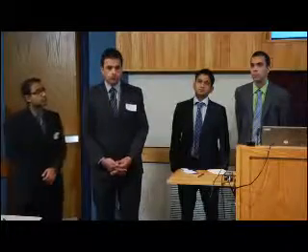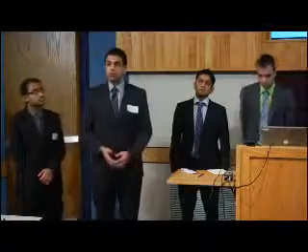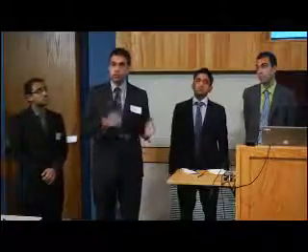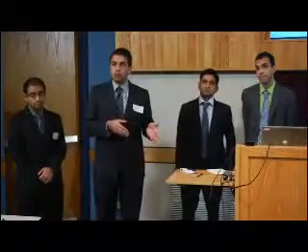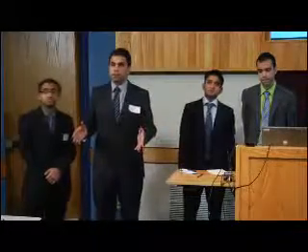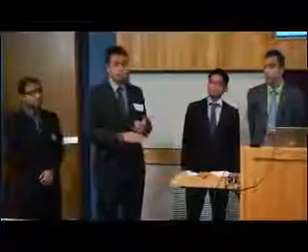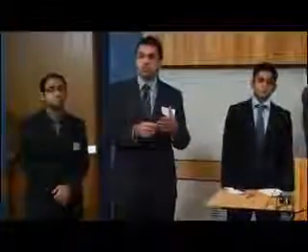Well, having just 1% of the flue gas stream would reduce the concentration of the nitrogen oxides in the flue gas. So for sure, the size of the reactor would be less, because the size of the catalyst and the reactor depends on the concentration and the flow rate of the flue gas going inside the reactor. But for SCR reactors, there's a minimum requirement of 2 catalyst layers. So in that case, it wouldn't differ in size very much, but just the height of the catalyst and the size of the catalyst would be different.